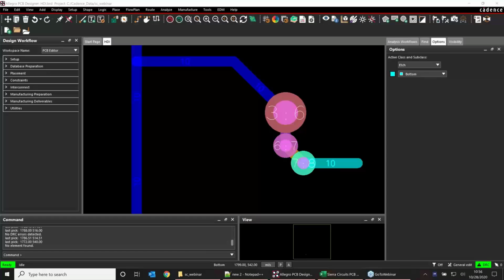If the differential impedance required is exactly double the single-ended impedance, then the trace width for the differential impedance has to be less than that for the single-ended impedance. Let me give an example. If you have 50 ohms at 5 mils and you want 100 ohms, then the width for 100 ohms has to be less than 5 mil.